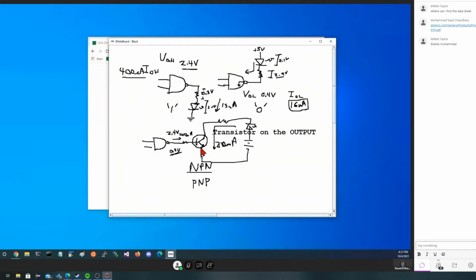But just for a practical purpose, for Halloween, in order to light up the monkey's nose, we could make that work. This circuit has the LED. This controls it from a gate. And we control the gate maybe with some switches or something. So just be advised that one sitting in the wild, if you ever see one directly controlling an LED and it's TTL, remember we're talking now about the characteristics of TTL, not some other technology, be concerned that the design may not be a good sound design.